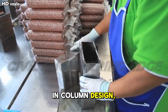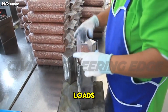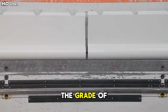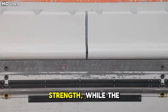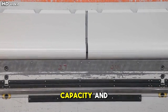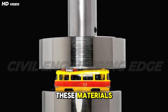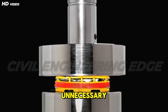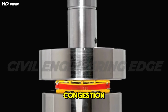In column design, material selection is governed by design loads, exposure conditions, and codal provisions. The grade of concrete determines the compressive strength, while the grade of steel influences tensile capacity and ductility. Proper proportioning of these materials ensures adequate load-carrying capacity without unnecessary increase in column size or reinforcement congestion.